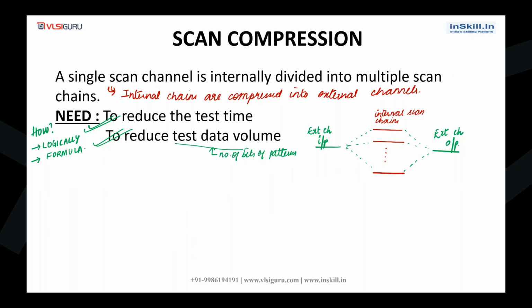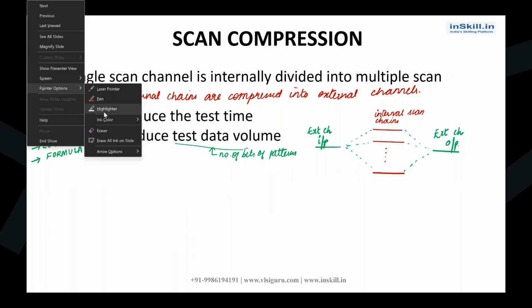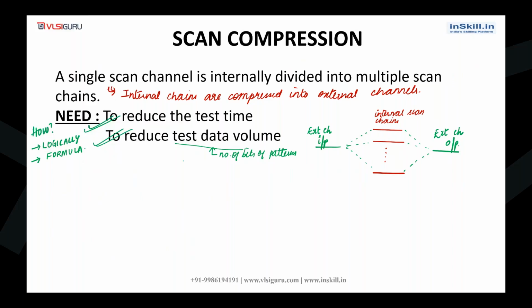Okay. Now, if you want to go for scan compression, you need to add a logic. If you're working with Mentor Graphics tools, you need to add a logic called the EDT logic.